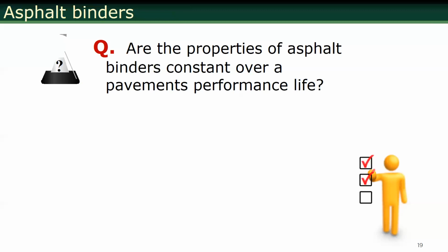tested 10 minutes after you leave it on the desk, tested 20 minutes after you leave it on the desk, you will see different properties. Binder doesn't age in that 10 minutes. There's a different mechanism that happens: temperature hardening. That's why when you look at the specification of binder testing, there are clear guidelines on when to test and what strain level to test.